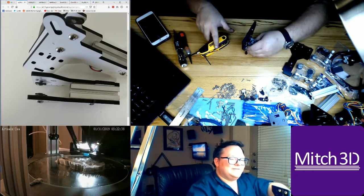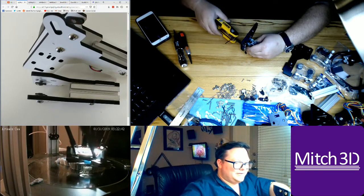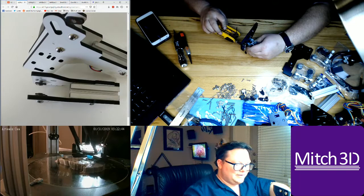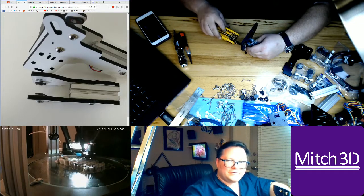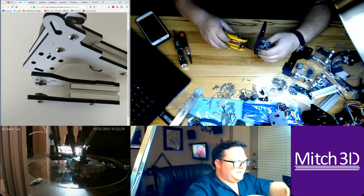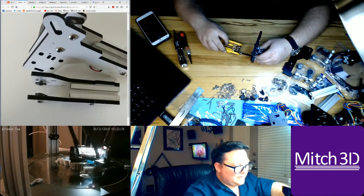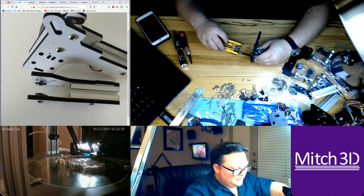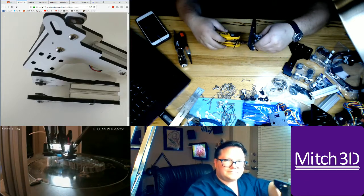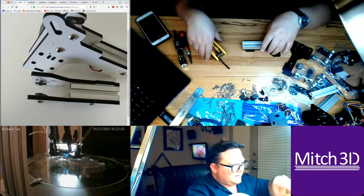It's just the crimping, I think, is what I don't like about it, and the fact that the thermistor is a screw-on thermistor. I will probably never build a hot end again that doesn't have a cartridge-based thermistor.